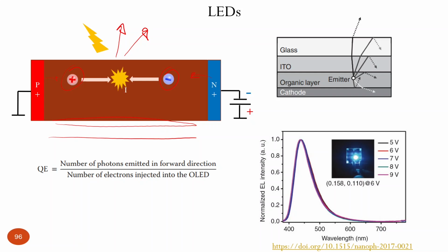This is similar to the most common photodiode, the characteristic LED device architecture for so-called organic and also perovskite LEDs, where we have PIN structures. And what do we need to get a good LED? First of all, we need to efficiently inject charge carriers in the active layer. Second, we need to organize radiative recombination. So again, no impurities, defects, and so on. It should be band-to-band recombination, to get out most of what is possible.